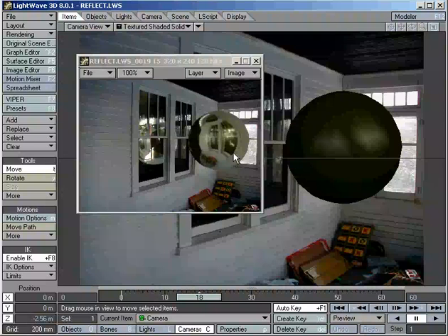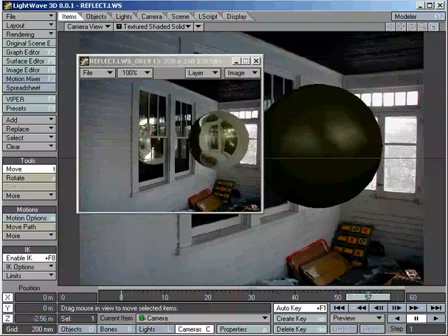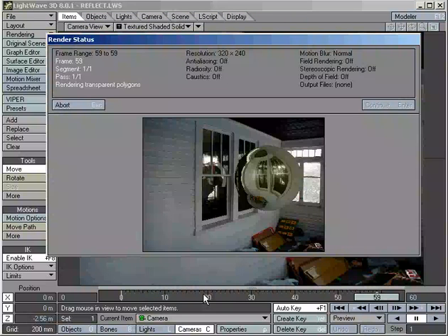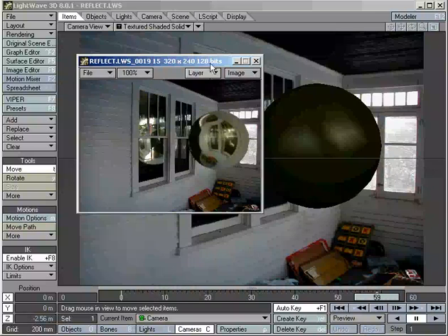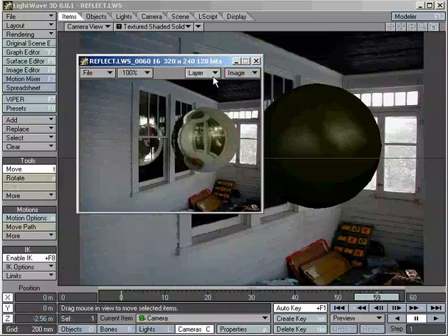As you see between these two images, the image map really isn't moving that much. What we need to do is create an environment. In fact, it's called a reflection box. And all a reflection box is, is just a box with this background image, or something similar to it, mapped on the inside so the reflection can see it. Now there's a couple of settings we'll need to do for that, but let's jump into Modeler for a moment.